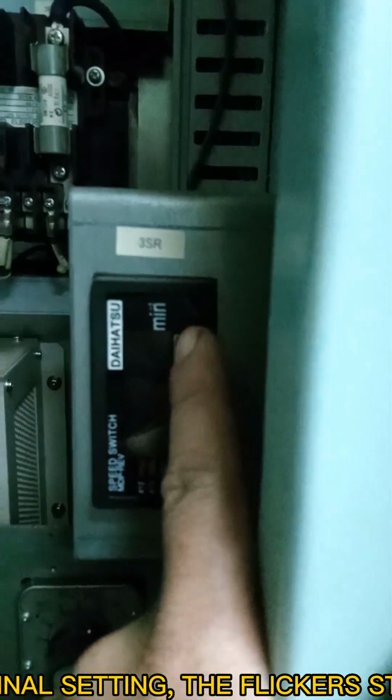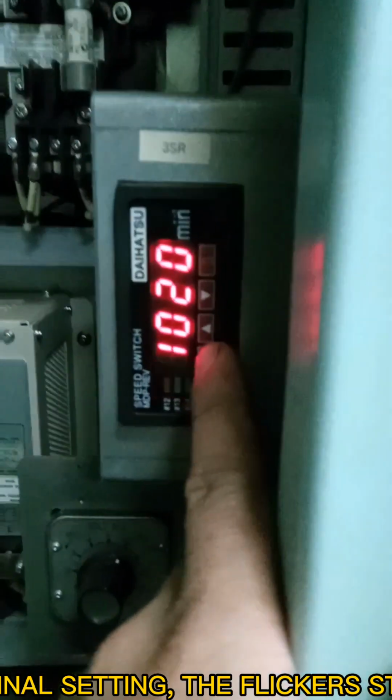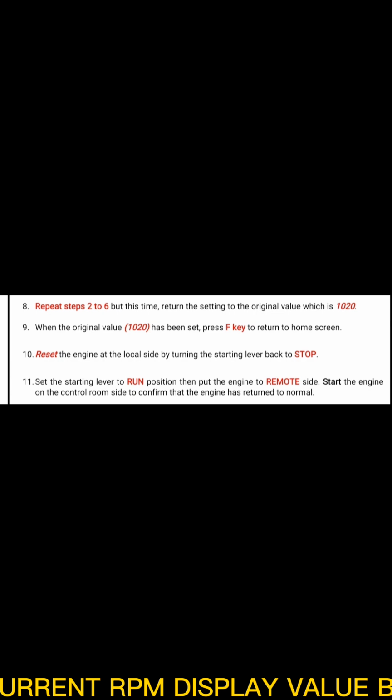Press the S key to register the original setting. When the flickering stops, this means the setting is already registered. Return the display to the current RPM display value by pressing the F key 2 times.